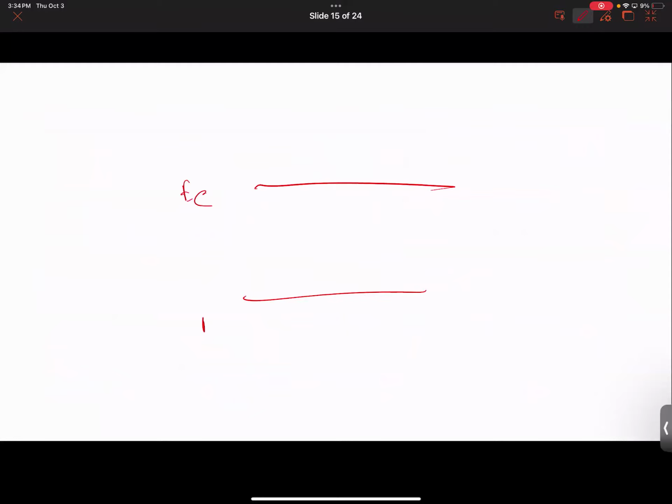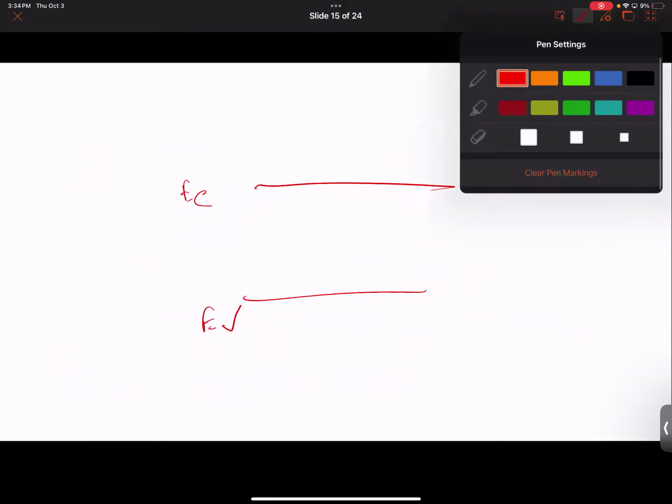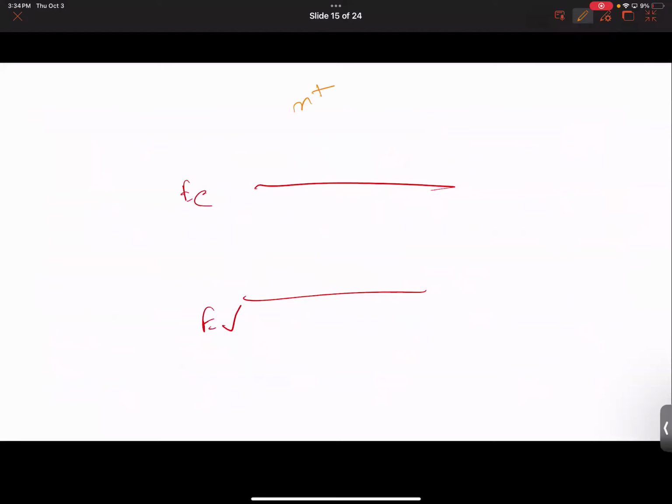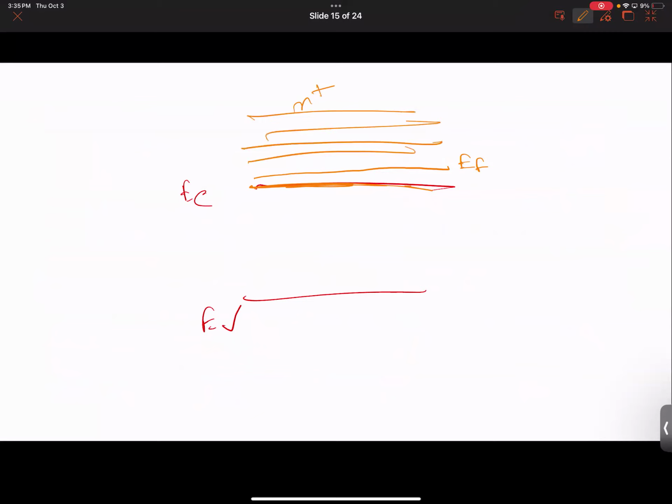If you have an n-type material, with EC and EV, and you heavily dope with n plus, the Fermi level could be inside the conduction band. Or, to simplify, many textbooks, rather than showing it inside the conduction band, just show it at the conduction band. It's all the same. Basically, you are already at the conduction band, so all the electrons at the Fermi level are available to conduct. Doesn't matter whether you're here, here, here. Basically, you have crossed the finish line, right?